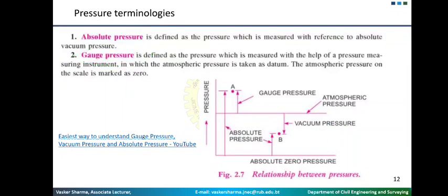For example, if you put air inside the wheels, like a vehicle tire, whatever pressure is inside, if you put a pressure measuring system on it, the needle will move, and as you remove it from the tire, it will go back to zero. That zero pressure is actually your atmospheric pressure. It is scaled like that. Actually atmospheric pressure is not zero, but it is referenced to zero.